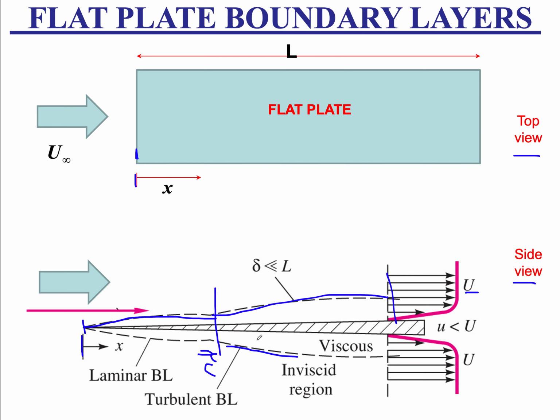So when we say that this is a viscous boundary layer, we're saying that the strain rate and the shear stress, the strain rate in particular, du/dy, is non-zero. Now we're defining our coordinate system y, measured from the surface of the plate perpendicular to x. That's in a side view. On a top view, the y will actually be coming out of the page towards us.